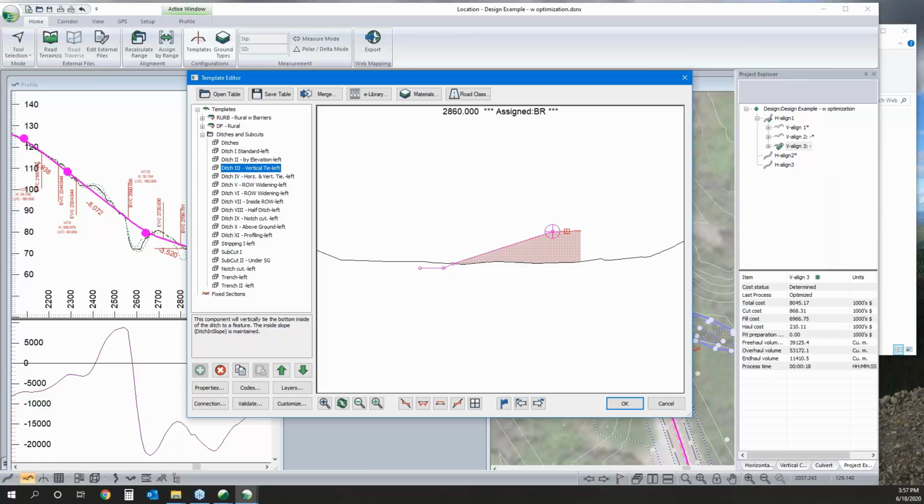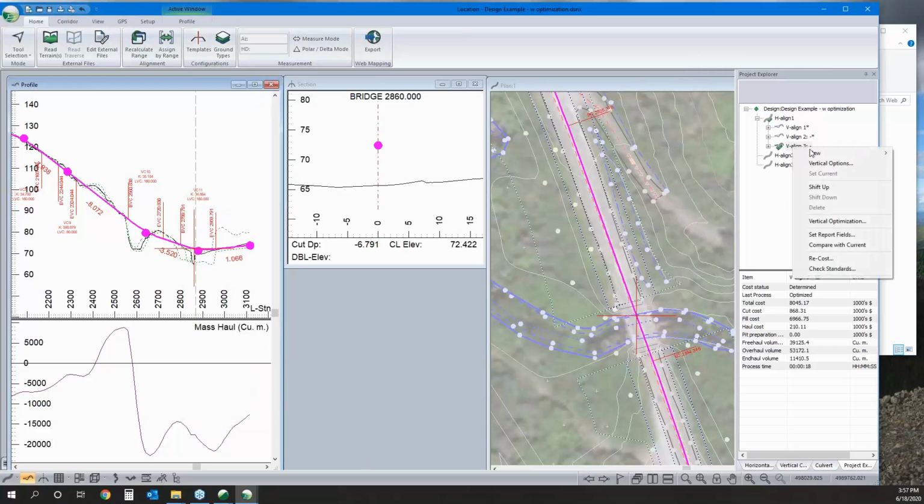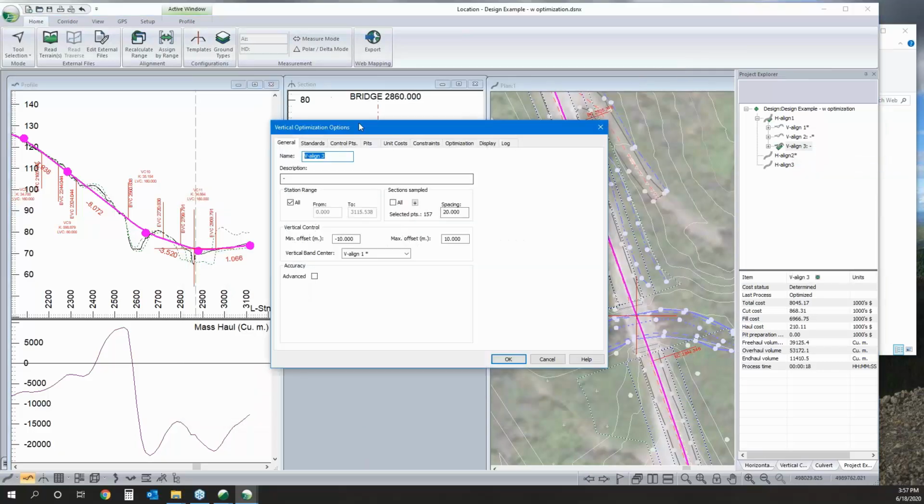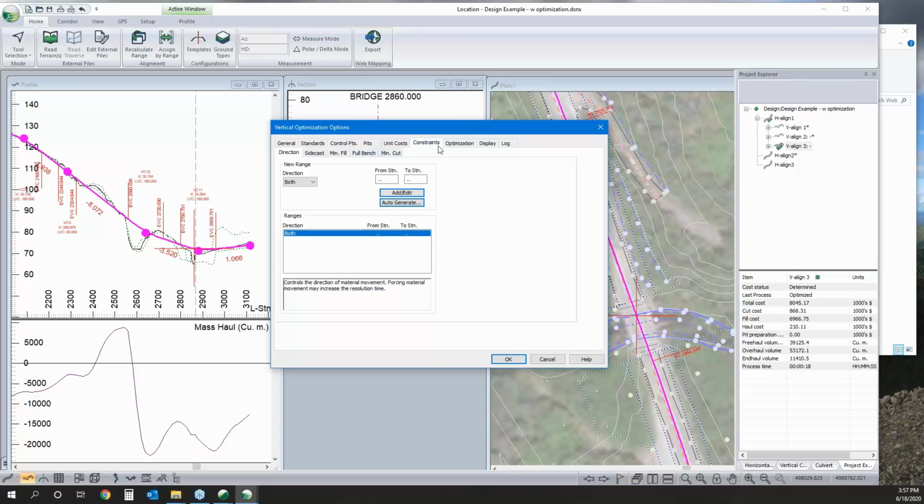How does the software calculate cost for sidecast? That's a good question. Sidecast is our kind of linear spoil site. That's assumed to be your free haul. So it's just the handling cost assigned to that movement. It's your free haul handling cost for that movement. So it's right there, descriptor.